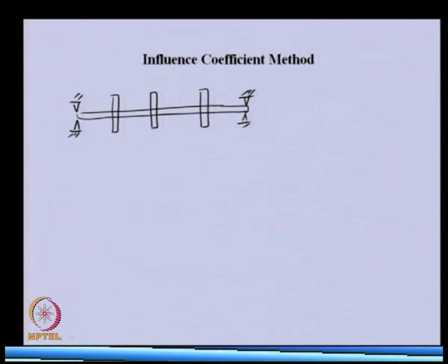Now, let us say these are disc 1, 2, 3, and we are applying a static force to disc 1. Because of this force, the displacement at disc 1 location, let us say that is x1, will be proportional to the force applied. So, if we increase the force in the same proportion, this particular displacement will increase.